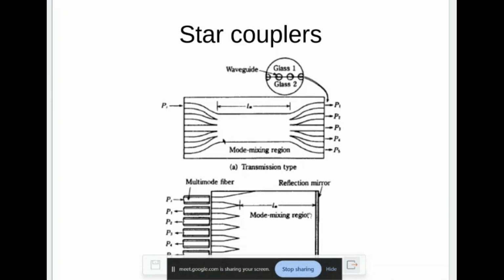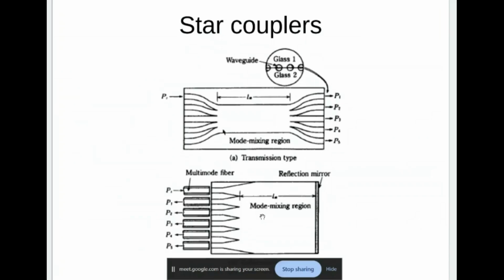Actually, not a mirror, but you cleave the edge such that it is perfectly reflecting. And so you can get redistribution. The challenge in both these problems is to distribute the power equally. From geometrical optics or lens design type of tools, you can work it out. Generally, it is not easy to get equal division, but it is possible.